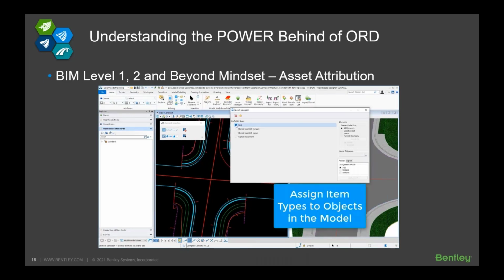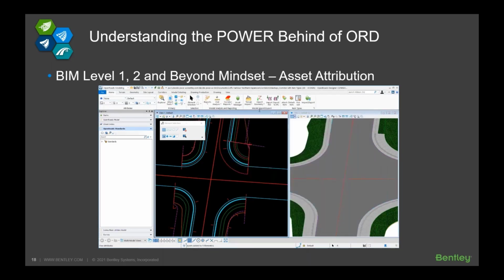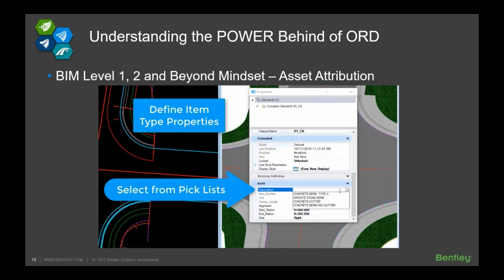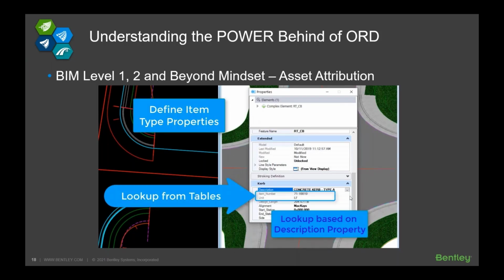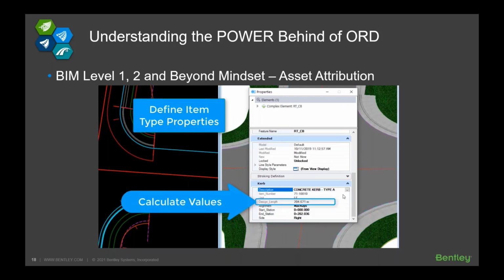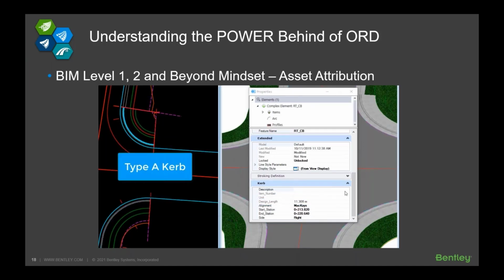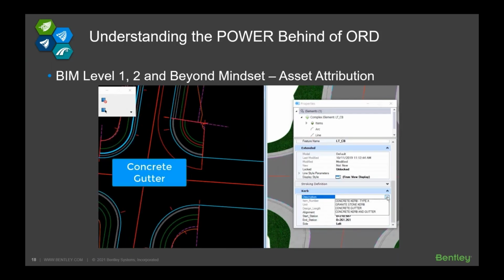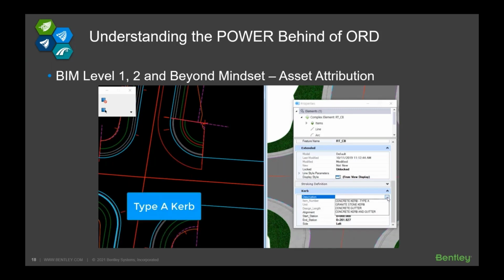Now, as an example, how does OpenRoads Designer have this kind of mindset? So apart from its information modeling capabilities, OpenRoads allows you to assign or create asset attribution readily by creating customized real life information. For instance, what is being shown here is information that you embed on a curve, giving you what type it is, maybe an asset number or asset tag, what its geometric properties are, and which chainage or station it is referencing in relation to your main highway or maybe other types of roads.